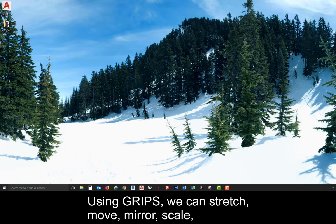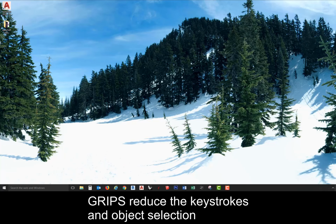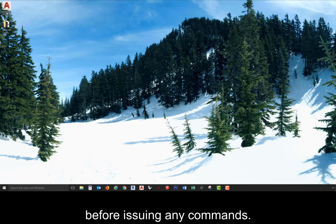Using grips, we can stretch, move, mirror, scale, rotate, and copy objects without entering commands or clicking toolbars. Grips reduce the keystrokes and object selection required in performing common editing commands. To edit with grips, we select the objects before issuing any commands.